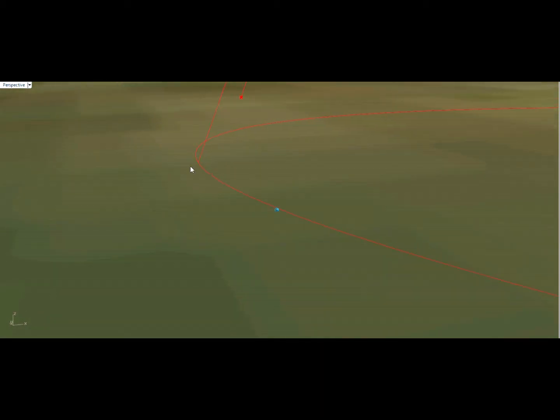Say if there was a sprung clamped carriage going around the rope, then you'd be able to bump up and over it, with sheaves underneath both sides and pushing against one on top, or wheels underneath pushing into a sheave on top. A better arrangement. It would probably be more forgiving to the sheath holding the rope down onto the anchor. So that would be a carriage transport system for the archway.